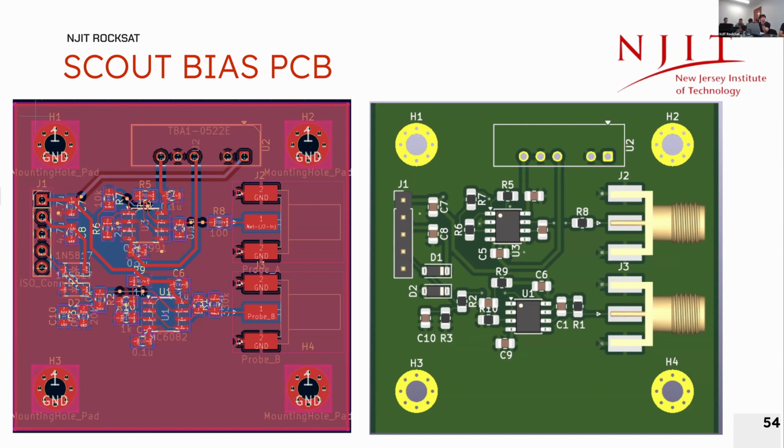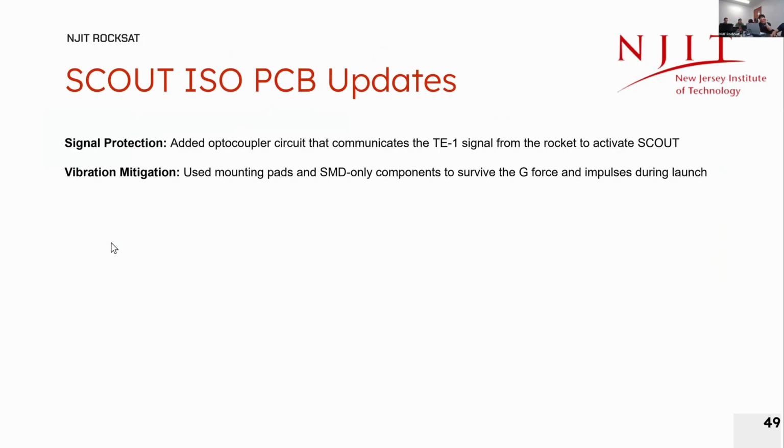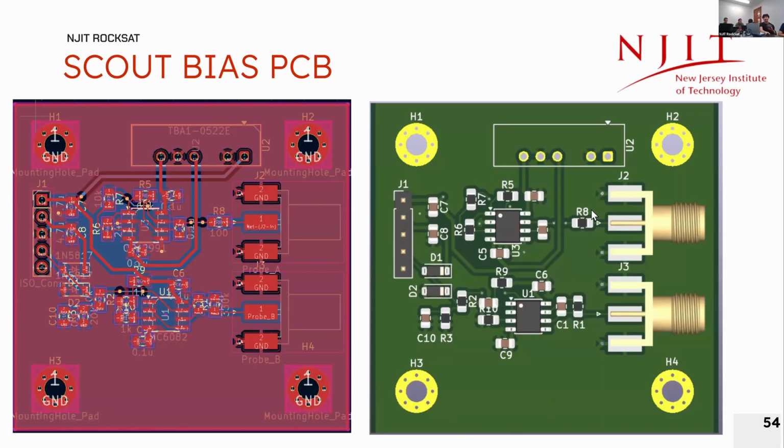Okay, I think in the 3D view it might be too far back. I wanted to have it hanging off the board a little bit, and I think it should clip in between the board. From what I see in the 3D diagram, I can't really show it here because I can't change it, but it basically just inserts into the board. When you look at the side, the whole cable part is clipping halfway through the board. I think there's an issue with the footprint, but the connection should be fine. I only made it horizontal so that it's not taking up too much vertical space. But if I double check and the vertical space is fine, I might opt for a vertical connection instead. Awesome. It sounds like you're already thinking about it, but that's great. Just one thing that caught my eye, and it's hard to tell from a 2D view. Yeah, right. No, great.